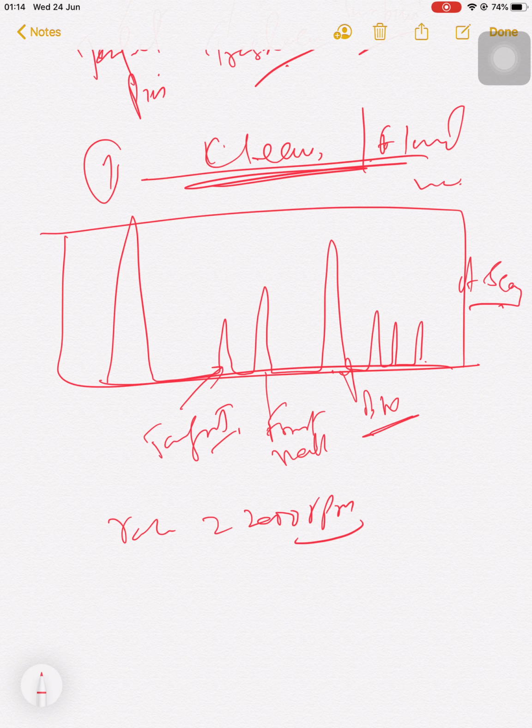So how you will interpret it: there are 150 readings per revolution and about 2000 revolutions per minute. The interface screen gives three results for better understanding. The B scan gives a 2D display of the transverse cut at any location of the tube length. The C scan gives the plan view of the tube rolled out flat, and the D scan gives a 2D display of the longitudinal cut at any circumferential position.